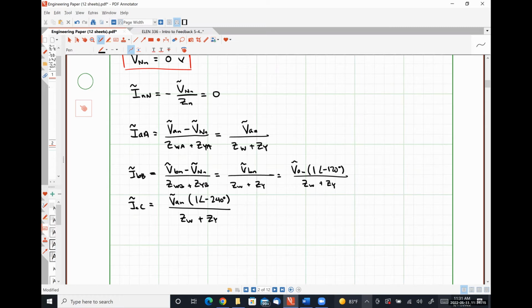As long as we have a multiple of 3 buildings, all of those unbalanced AC systems or HVAC systems look like a balanced load to the transformer that's servicing all of them. Right, so you can design systems where you have repeated elements and place them between specific phases in order to mitigate that unbalance, or at least minimize the amount of unbalance that you have.